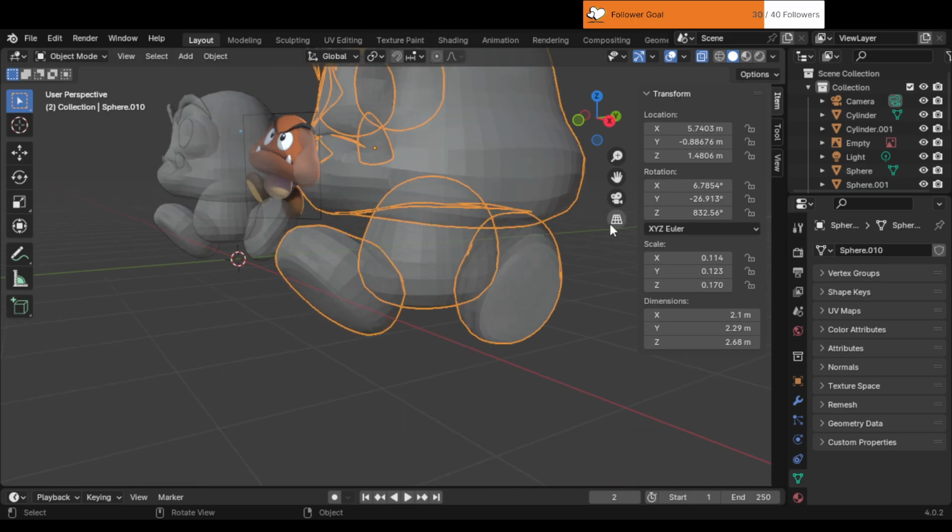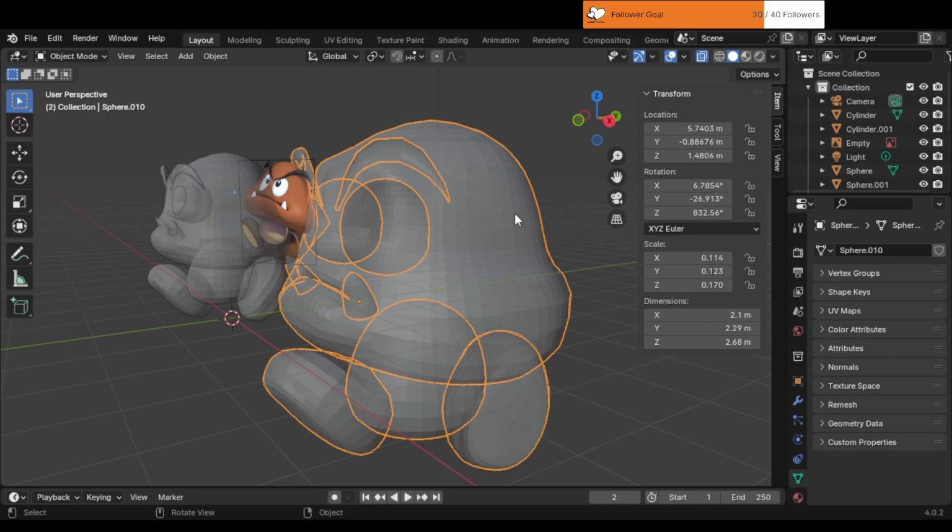In Blender, if you have multiple meshes that have been joined into a single object and you want to unjoin them back into separate objects, you can use the separate operation. Here's how to do it. Unjoining meshes. 1. Select the object.